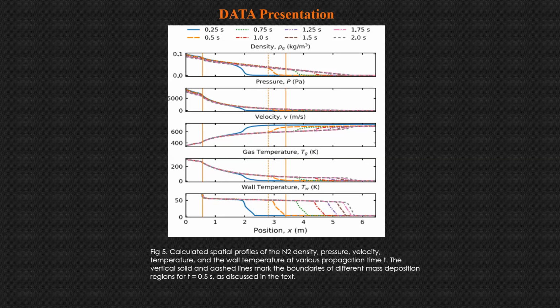This profile shows 3 distinct regions. The first one is the inlet region. The gas pressure and density in this section are not constant, and they slowly decrease with time due to the drop of the buffer bank pressure during the discharge of nitrogen.